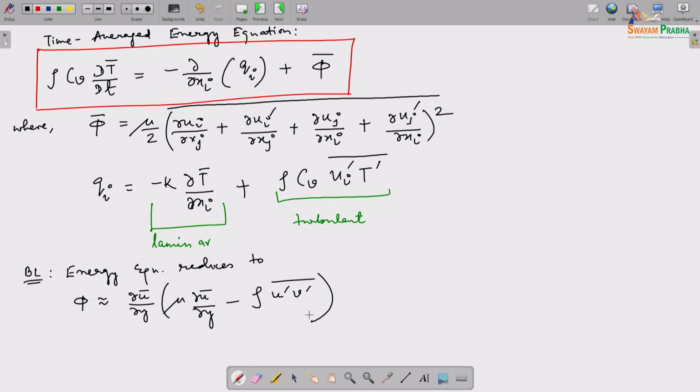I think it's kind of a little off question because we're specifically talking about turbulence here, but I just wanted to point out that essentially what is happening in a boundary layer is that the velocity in the direction of flow, which is u, right, its fluctuation is not trivial in the y direction, the direction perpendicular to its flow.